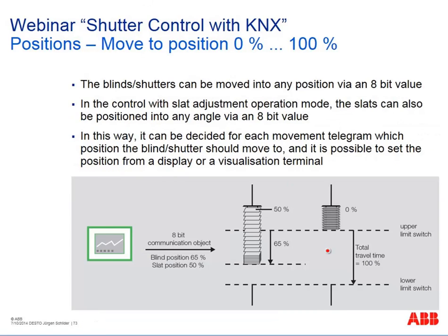And furthermore, if you would like to position your blinds directly via a one byte telegram, sometimes also necessary from a visualization, for example, it's possible. We have communication objects for both blind position and lamella position. If you send a value there, it goes directly to this position.